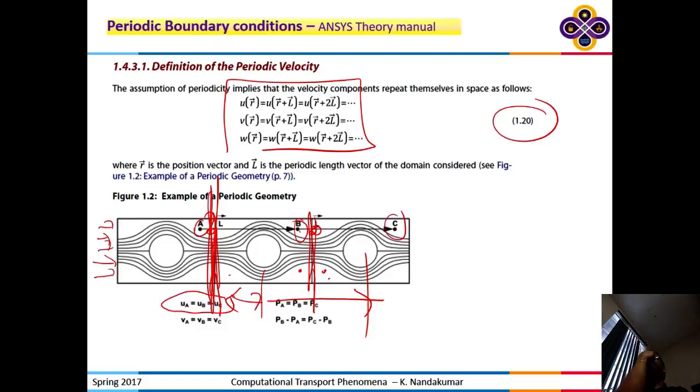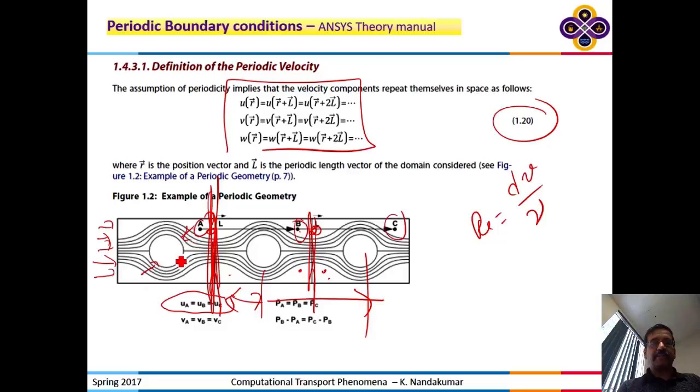Can we give a precise definition for Reynolds number? There is no unique, precise definition that you can apply universally. But what you can say is you need to choose a length scale, a velocity scale, and a fluid property. So the Reynolds number is defined as dV over nu. Nu is the property, okay? But you need to choose what d is. In this case, you have 2 choices. You can base it on the diameter of the cylinder, or you can base it on the height of the channel. There are 2 Reynolds numbers that you can define.